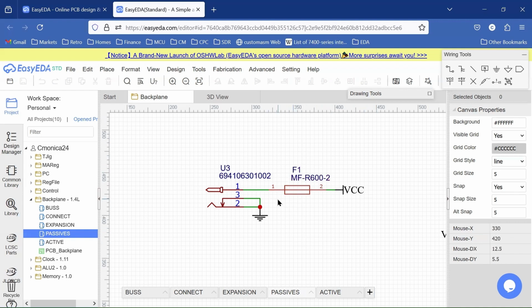So what happens is this is going to have an 8 ohm resistance when the power is just turned on. So that's going to limit our current to a little bit over half an amp. And so that will allow the capacitors to charge slowly up to the operating voltage. And then this is going to start to heat up.